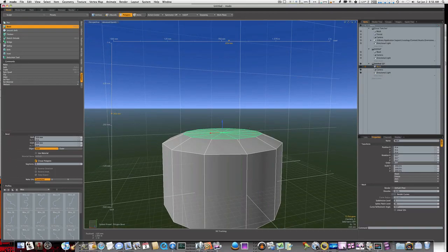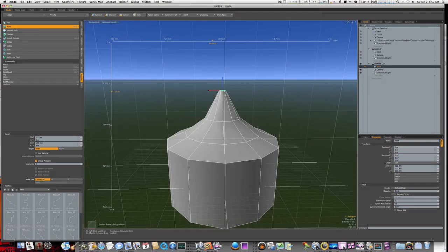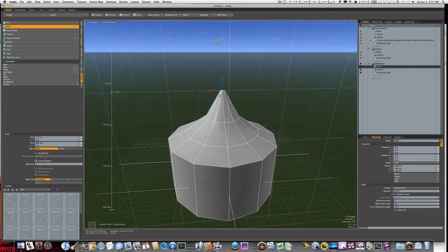Okay, now I'm going to hit the shift key and click once, and that will reactivate my tool without me having to drop it and go back over to my shelf and reactivate it. You just hold shift and left click and it reactivates the tool. As you can see, now it's reactivated. Let's bevel again, bring it up, and bring it in like that. Shift click, and let's bring it way up here like this and bevel it in. Okay, now we got that.